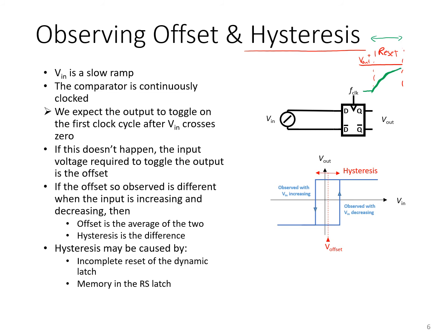So in such a situation, V out minus in this case would not perfectly reach VDD before the next regeneration phase starts. So that's going to give V out minus an inherent head start, if you like, in the race to the bottom, as we've been calling it.